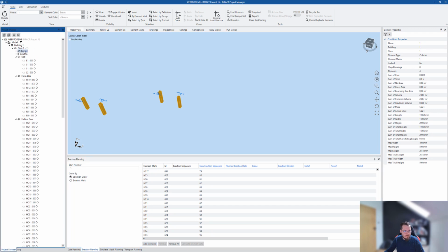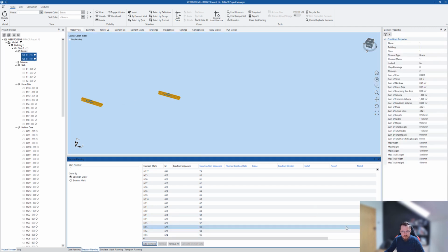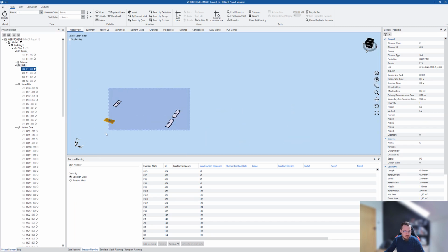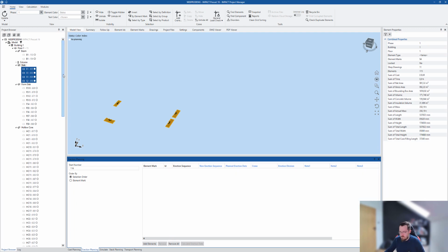For demonstration purposes, I think we're good. You can of course fence over the elements as well, add everything, beams, columns, and yeah, balcony slabs as well. And I think we'll be good. Add those elements and apply. I'll apply that to the model. There's also, I think, pre-stressed slabs, but we'll verify soon enough.